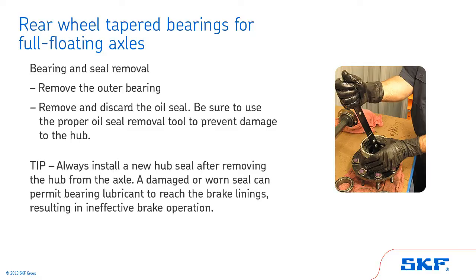Tip: always install a new hub seal after removing the hub from the axle. A damaged or worn seal can permit bearing lubricant to reach the brake linings, resulting in ineffective brake operation.